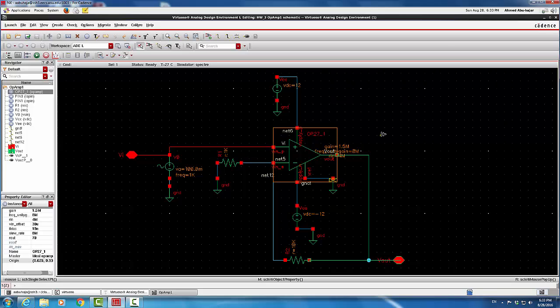And then we ended up having an AC sweep, which is basically a frequency response of the circuit, and that is by varying the frequency of the input signal from 1 Hertz to 1 megahertz to 10 megahertz. And we realized that this op-amp, or the entire circuit, behaves as a low-pass filter.